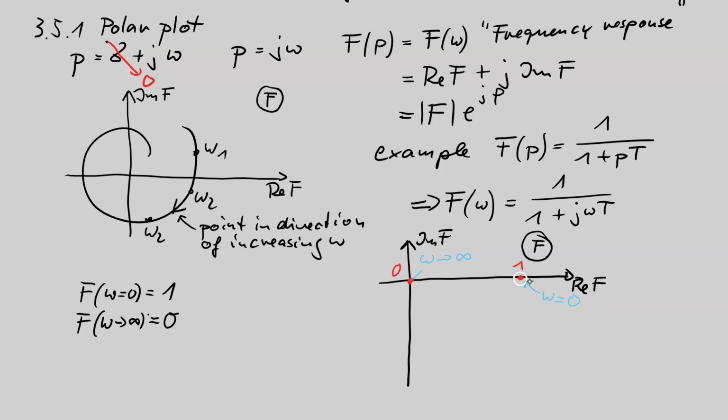Yeah, with 2 points I cannot define which type of curve this is. We know from mathematical scientists that a function which has only a linear part in the numerator and a linear part in the denominator, because this bilinear function has a polar plot, which is either a straight line or a circle. With 2 points we cannot find out if this is a straight line or a circle, so we need a third point, and this comes now.